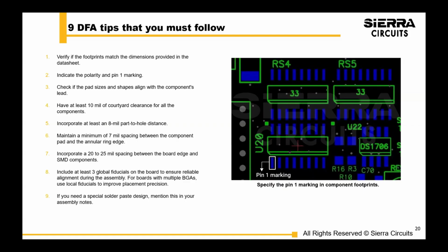And then lastly, I'm going to give a shout out to fiducials. Fiducials are important as the boards are either getting more dense or if the boards are very large, board material moves around. So it's not what you see in the data is what you get physically. And so assembly shops need fiducials to align to their equipment. So fiducials are important, and if you can have a fiducial on your board next to a sensitive component, that's even better. Otherwise, we'll probably end up putting fiducials on railings for the array.